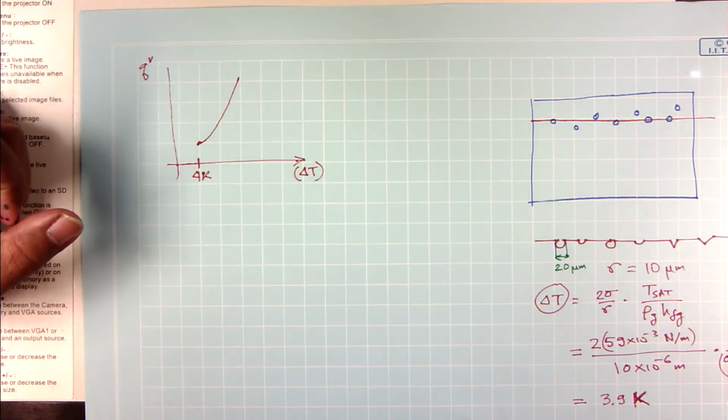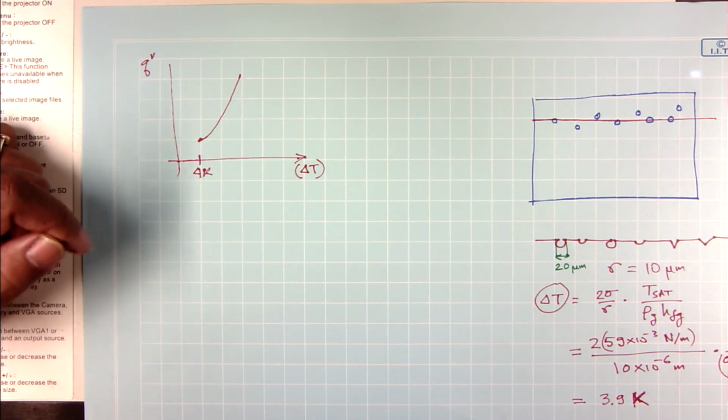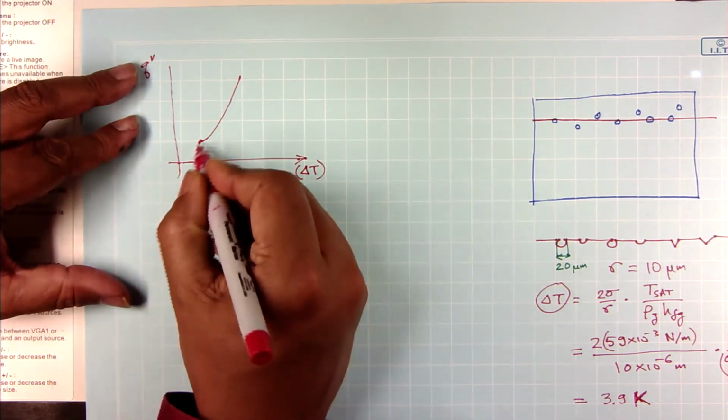Does that make sense? So, as long as my heater temperature is less than 104 degrees Celsius, I will not nucleate a bubble. So, I am going to form a superheated liquid very close to the surface of the heater, but it will not nucleate a bubble. Okay. So, what happens? How does the heat transfer occur before the first bubble hits? Natural convection.